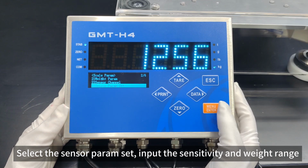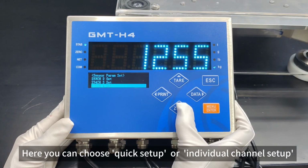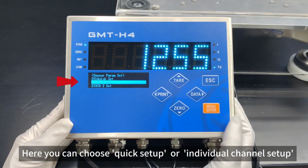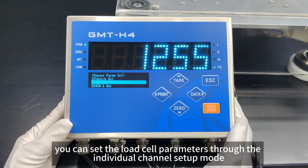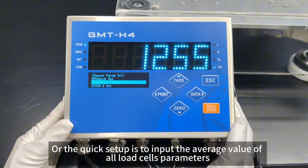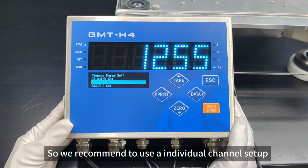Select the sensor param set, input the sensitivity and weight range. Here you can choose quick setup or individual channel setup. GMT-H4 has 4 channels. You can set the load cell parameters through the individual channel setup mode, or the quick setup, which is to input the average value of all load cell parameters, which may affect the accuracy. So we recommend using the individual channel setup.